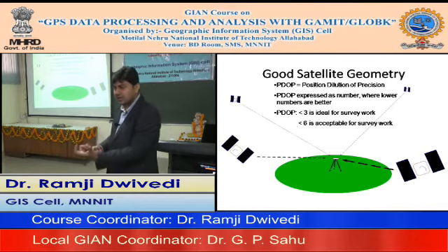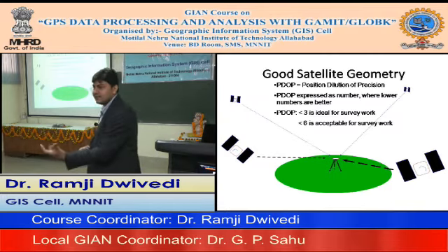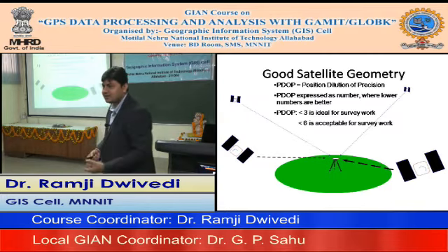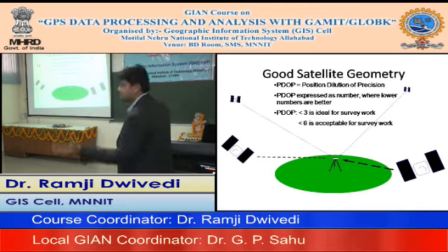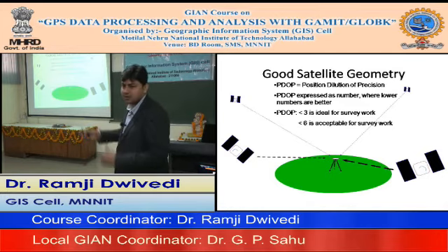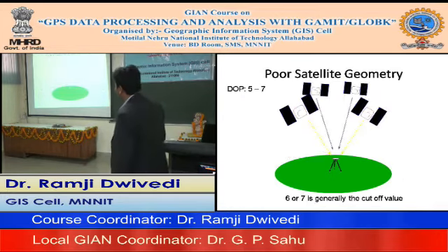We were a little worried that if it stayed there for at least half an hour or 45 minutes, what would happen to the data set? But eventually it dropped to 2.5 or 2.7 something. So obviously less than 3 is ideal for survey work, the high quality work, and below 6 is acceptable, but beyond 6 is not acceptable at all.